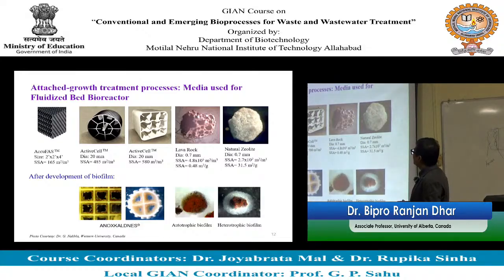In addition to plastic media, those are more commercial plastic media. You can see some commercial names, like Activcell and Aquafus. But you can also use other inert media, like lava rock, which is more like a natural biomaterial. There could also be natural zeolite. Those are before biofilm formation, and those photographs show the media after biofilm is formed. If I compare this one with this one, you can see that in the interior portion of this media, biofilm has formed.